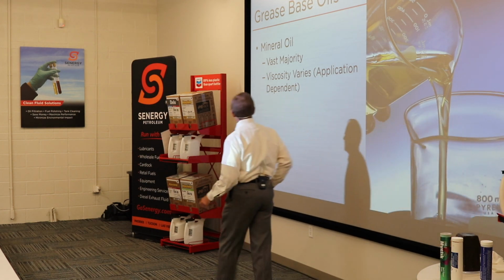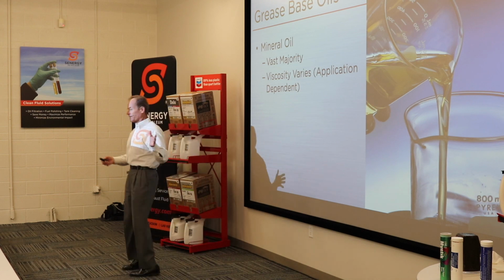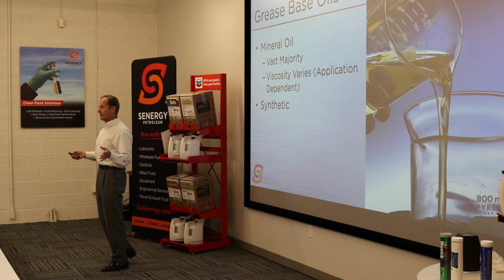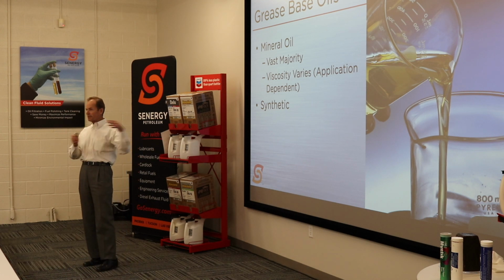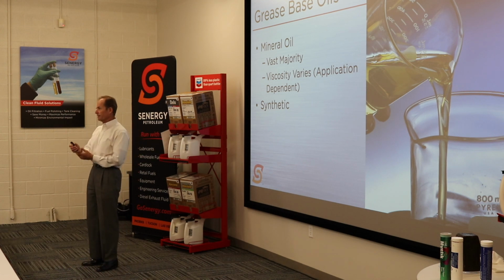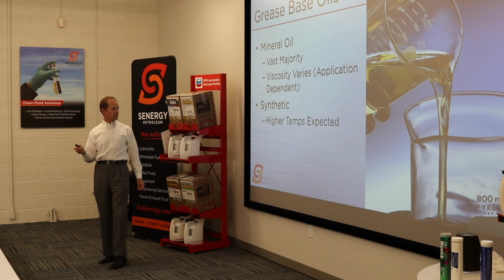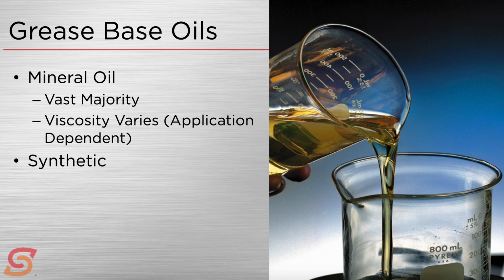Okay? So that's the viscosity difference story in our greases. Now you do have some greases that are synthetic, or the base oil inside the grease is a synthetic. Like I said, they're just rarer. They're not impossible to find by any stretch. You will use those, or you want to use those, where you're expecting higher temperatures. Okay, if things are going to get hot, it just makes sense to have a synthetic in there to resist the oxidation that's going to come up and to behave better at the higher temperatures.